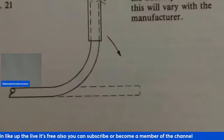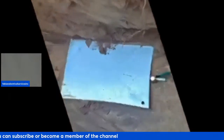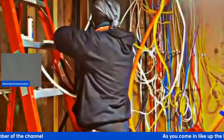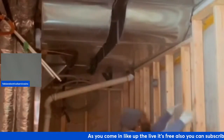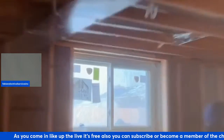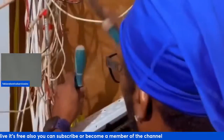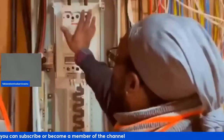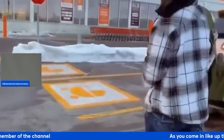Key features to look for: Joule rating. This indicates the amount of energy the surge protector can absorb before it fails. A higher rating offers more protection. Indicator lights: some surge protectors have lights to confirm they are functioning correctly and protecting your devices. And data line protection: some models offer additional protection for data lines such as coaxial and Ethernet cable.